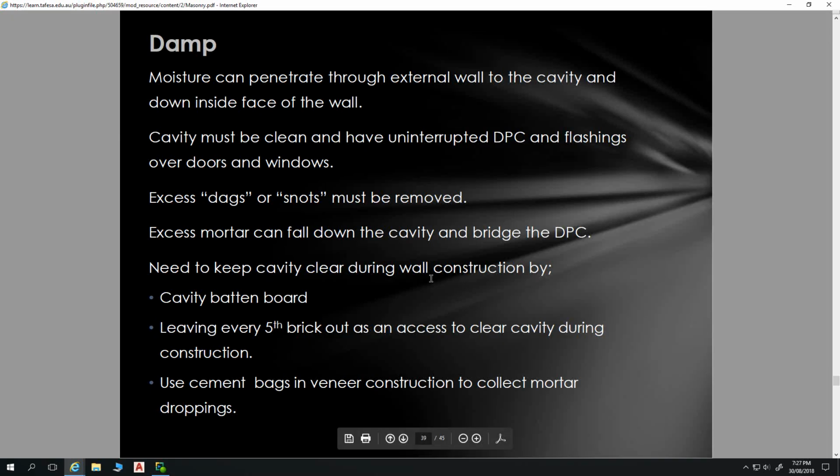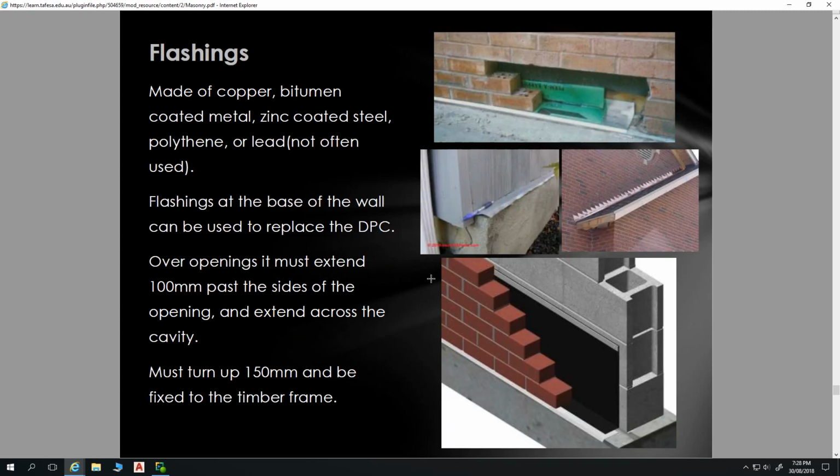So, ways of doing that. To ensure that your cavity doesn't get breached, you have to remove the excess bits of mortar, and that can be done by packing the cavity with old cement bags and things like that. Or you can leave bricks out, and then you clear out the mortar, and then you prepare a brick with mortar, slide it in and trim up that mortar at the base when you finish the wall.